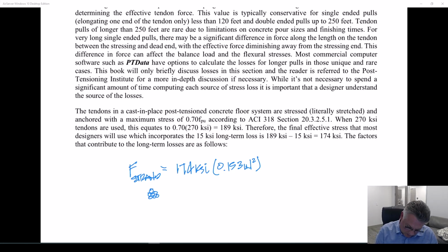So while that diameter may be 1/2 inch, the total area of steel within that 1/2 inch isn't equal to 1/2 inch of steel. So that's why this is not 0.2, which is what it would be if it was truly 1/2 inch.